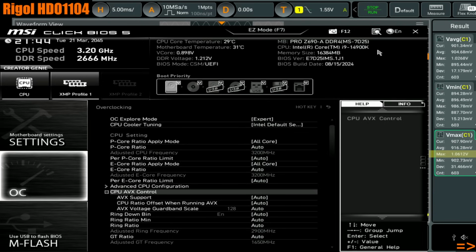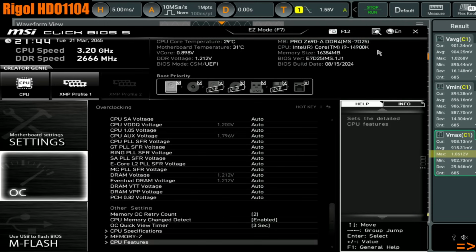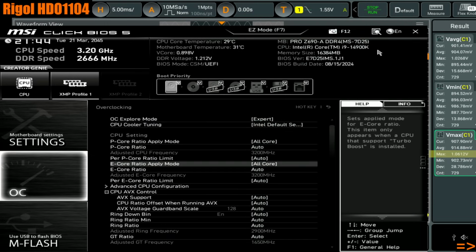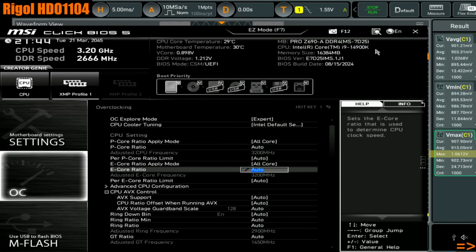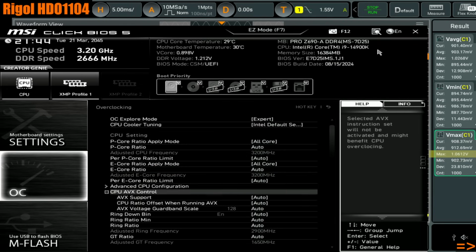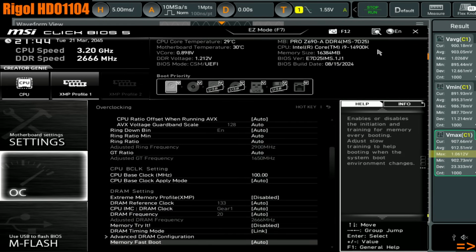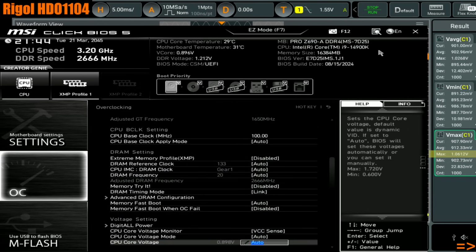Now, with Intel default settings, Intel is imposing a limit of 1.55 volts, which I hope for Intel's sake is low enough. But if you're paranoid about the longevity of your CPU, and your motherboard has the VR voltage limit setting, you can just set a lower limit. Unless you have an MSI motherboard, because then you don't have that setting, so you can't do that. But anyway, we can still do some things about the high voltages that we're getting on this board, and we can also slightly improve the performance.